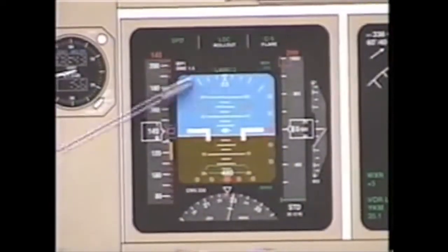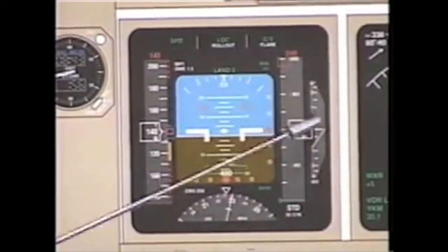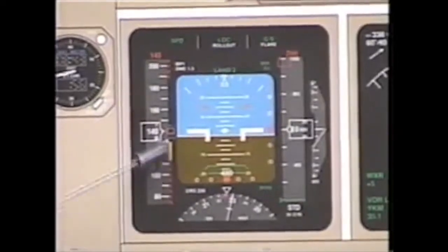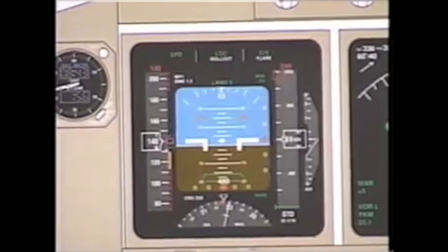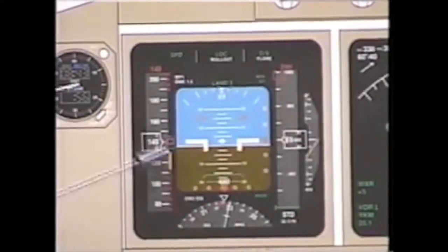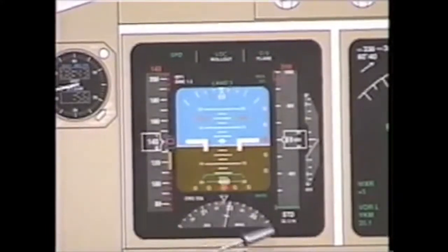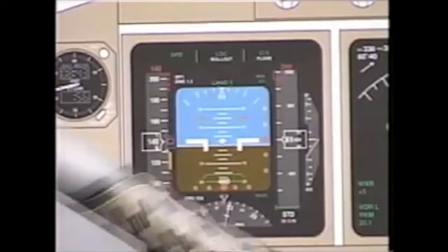The IRS will generate the attitude picture and the IRS heading. The accelerometer portions of your IRS will give you vertical speed and the green airspeed trend arrow. The attitude position of the IRS will shut down the accelerometer portions. As a result, the vertical speed and airspeed trend on your PFD will be lost. However, the attitude mode of an IRS will retain the attitude picture and the IRS heading. The heading will have to be updated occasionally through the CDU page, position page 2.